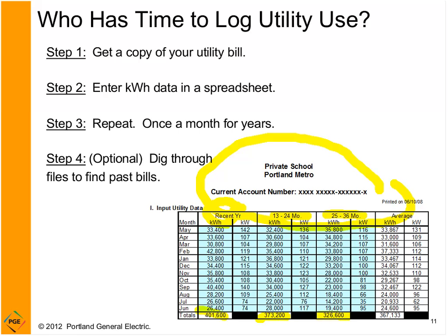But in the case of a customer who has this type of steady increase of energy consumption, maybe they can't identify a change that's gone on, or they can't comfortably say that yes, this energy consumption increase makes sense for me because of X, Y, and Z. Maybe they have this increase and they haven't made any major changes to their processes. That would indicate to me that this would be a prime candidate for some tune-up and/or commissioning opportunities.